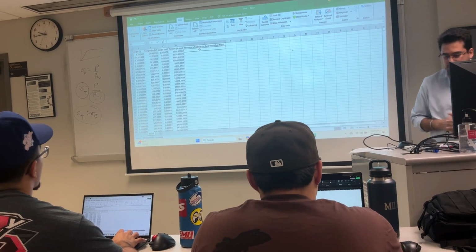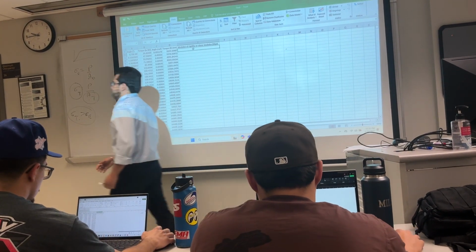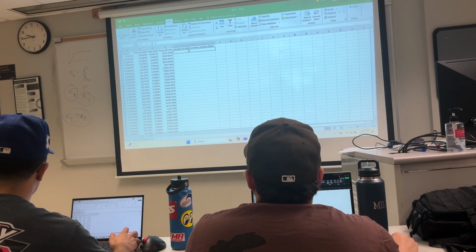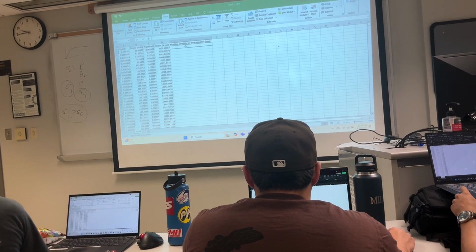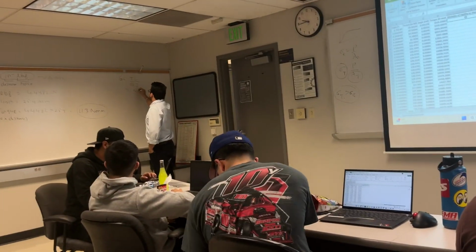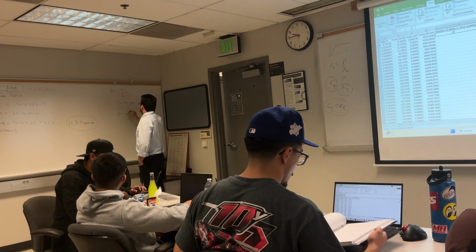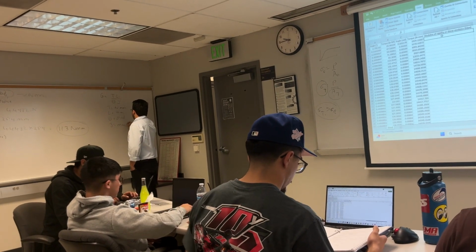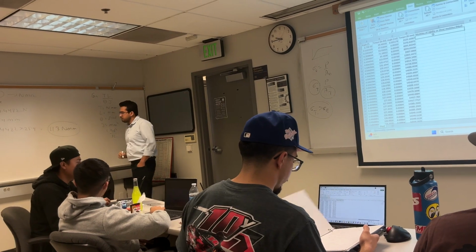Okay. What's the formula? It's torque over J equals G theta over L, so G is torque times L over J theta. T is in Newton meter, L is there, theta is in radians. J is in mm to the fourth, which is equal to pi d to the fourth by 32, right?